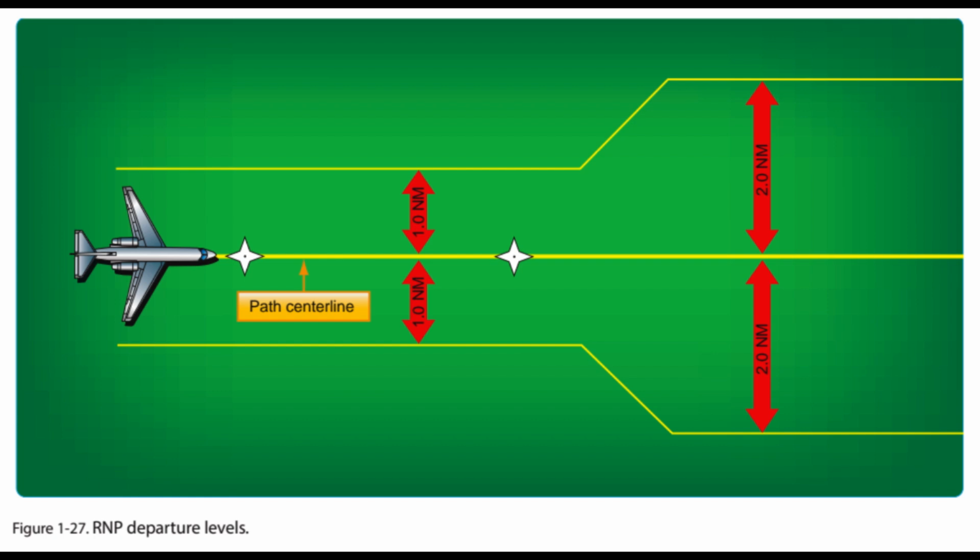RNAV routing is part of the National Airspace Redesign (NAR) and is expected to reduce complexity and increase efficiency of terminal airspace. When new RNAV departure procedures are designed, they will require minimal vectoring and communications between pilots and ATC. Usually, each departure procedure includes position, time, and altitude, which increase the ability to predict what the pilot will actually do. RNAV departure procedures have the ability to increase the capacity of terminal airspace by increasing on-time departures, airspace utilization, and improved predictability. All public RNAV SIDs and graphic ODPs are RNAV-1.